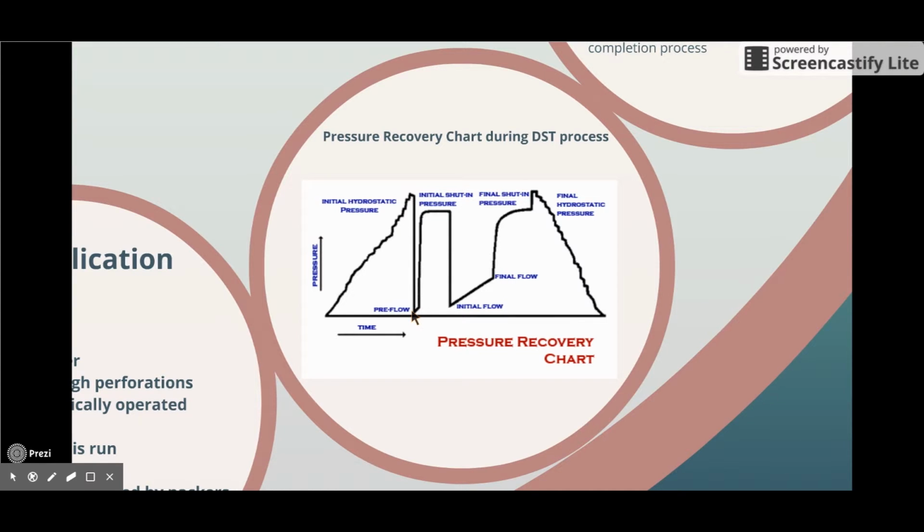The shut-in valve is closed. The first build-up period is started. The first shut-in period. The pressure increases as the fluid below the shut-in valve is compressed due to the pressure build-up. This can be seen in the graph as increasing.